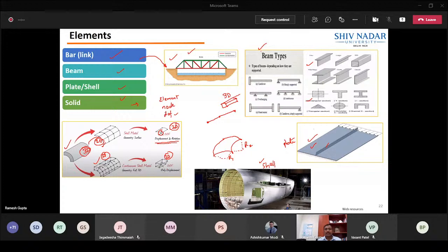Now the question comes: why is there an additional degree of freedom in rotation? Because we are looking at the mid surface. Then what about the surface which is above or below? That will be dictated by how the mid surface is rotating, or how your normal is rotating. Based on that, from the 2D surface itself, you are able to analyze the entire 3-dimensional body. Truly speaking, your 2D element is able to model or analyze a 3-dimensional structure. That is what I want to emphasize and showcase.